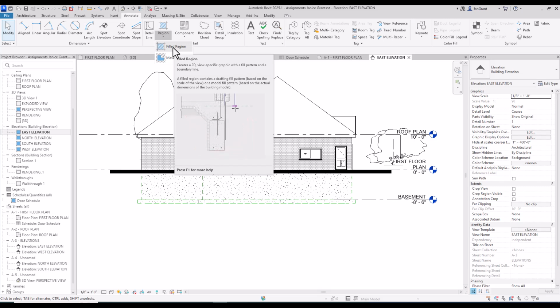If you take a look at the little video there, what they did was, in a detail, you can create the boundary and then get that earth hatch in there for your foundation details. I mean, this is where you're starting to get very detailed and bringing in your anchor bolts and your 2x4s and all of the materials that are components that you would load and then create that detail.